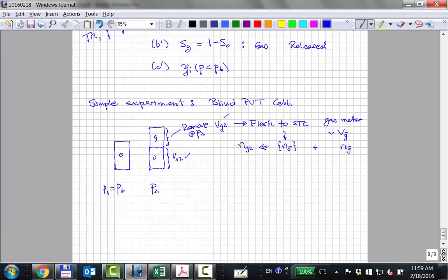Okay, so if you've got the volume, the moles, the pressure and temperature, you have the Z factor. So you've got the moles, the volume, and the pressure, so we can calculate the Z factor of gas, and that's going to be reported by the lab. So that's equal to the pressure, volume of gas removed, R, reservoir temperature, and missing something, number of moles removed. And so they calculate that Z factor.